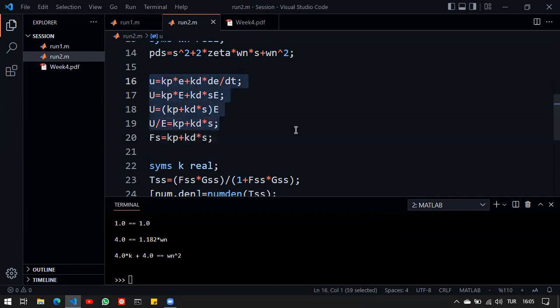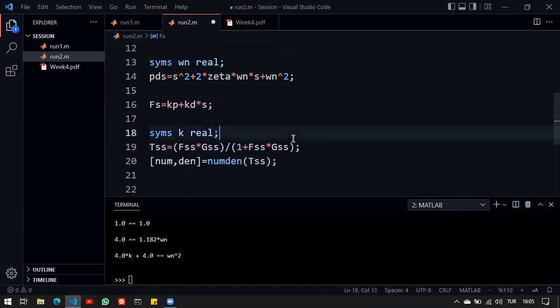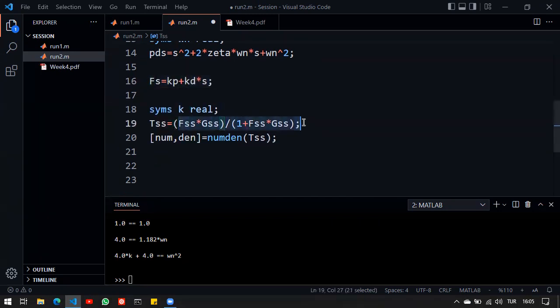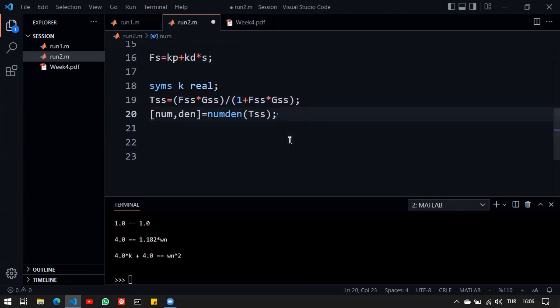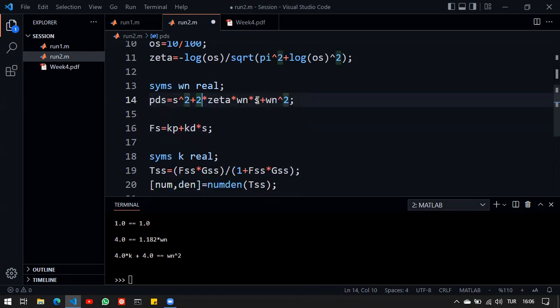Now, the only thing that will change in terms of design, if you're using the polynomial coefficients method or the algebraic method, is the definition of your controller. You will always use the structure of the controller, calculate the closed loop transfer function, and get the characteristic polynomial and its coefficients. And on the other side, you again need zeta and omega n values in order to determine your transients, and then you will construct the polynomial in order to build the problem, which is the coefficient equation method.